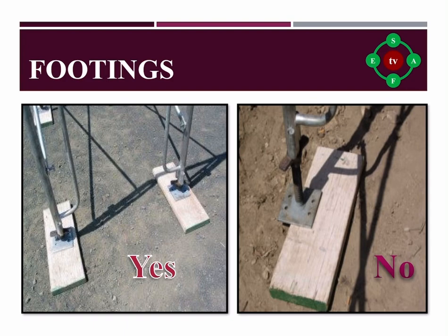Footings. Scaffold footings have to be leveled and have the capacity to support the loaded scaffold. The legs, poles, frames, and other upright components should carry the weight of the base plates and mud sills.